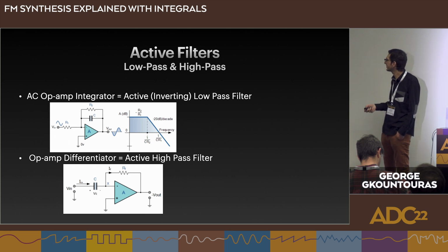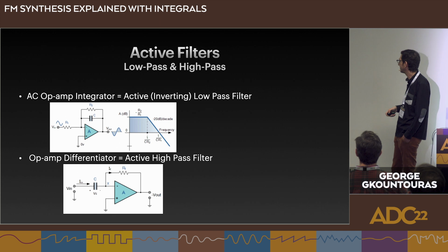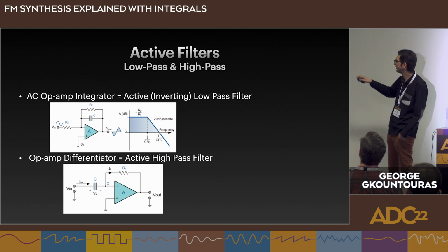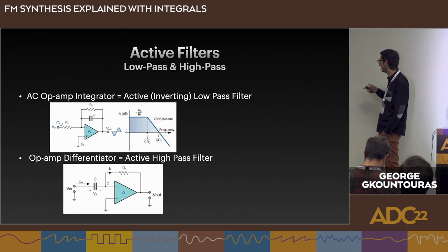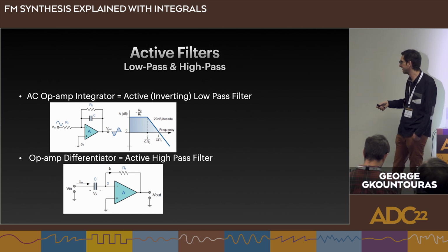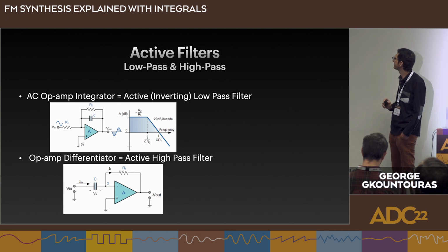We see the low-pass behavior of the op-amp integrator. And again, there's some extra stuff, but don't worry about that. And the differentiator is the opposite thing. It acts as a high-pass filter.